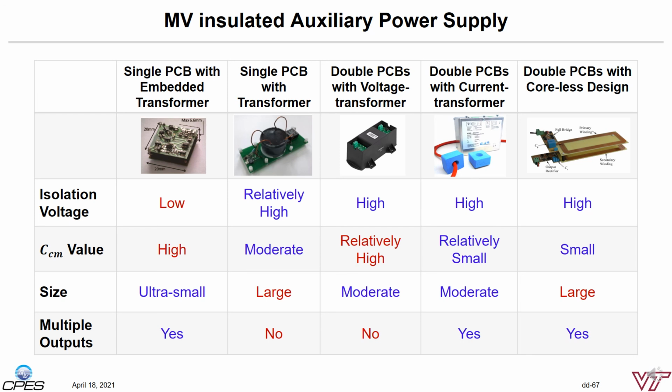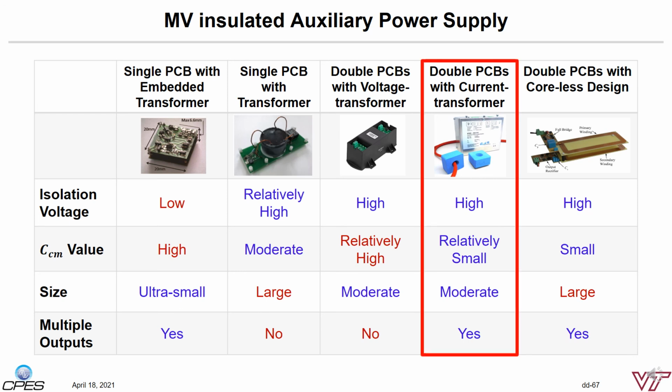Voltage-based design is more common as it follows the typical design process, but the design will be difficult to supply multi-channel loads. In that regard, current-based transformer design can easily offer a modular approach for multiple receiving loads. Therefore, in order to drive multiple loads, we choose a current transformer-based design with separate PCBs for the input and output circuit. It offers the balanced performance between power density, functionality, and insulation capability.